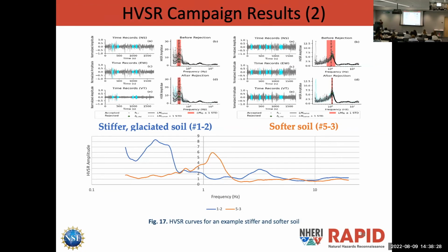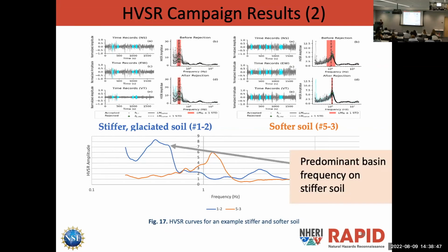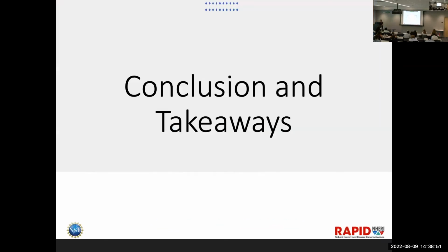But breaking down a more detailed view of the HV outputs, the spatial trend was really puzzling initially, but we found that the really short frequency matches the frequency of the surrounding basin. Because the basin is so large, it resonates at a really low frequency. And we verified with some people from USGS that this matches the basin based off of previous earthquake recordings. So that's our current theory for that. There's where the frequency is.